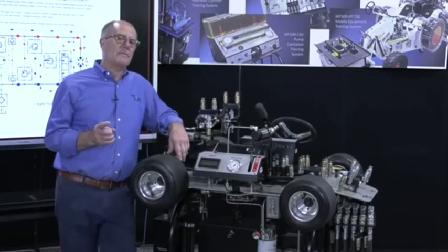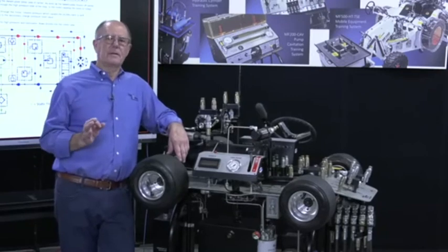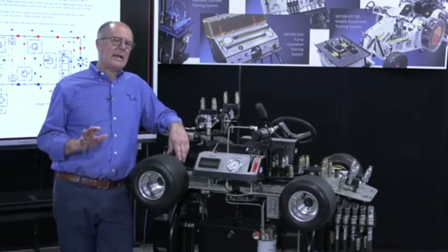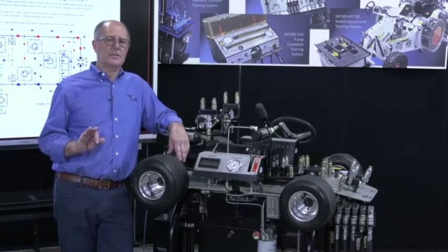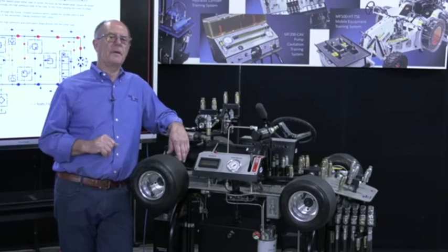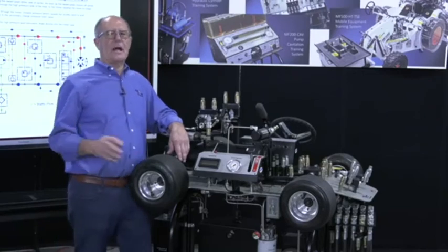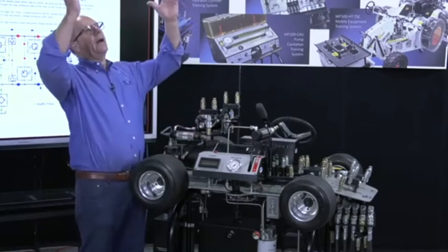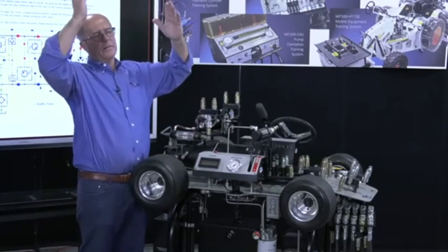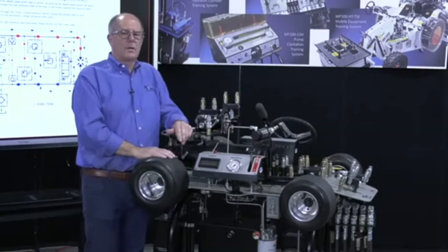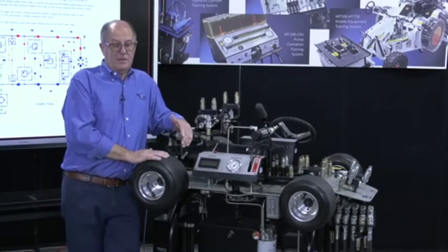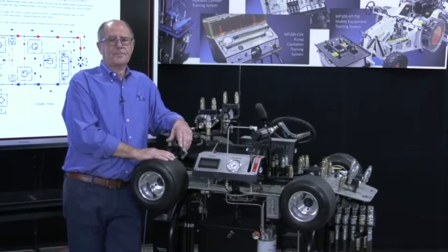But the beauty of micro leak testing has got to be safety. You can't beat it on the safety. Meaning this, you can test 98% of the components in any hydraulic system without starting the engine. Well, think about that from a safety point of view. I've seen people take 994 Cat loaders, raise the bucket in the air to try to check for leakage on one of the lift cylinders. It's the most dangerous thing in the world. And it's not because it's a 994 that it's dangerous, it's just a dangerous procedure.